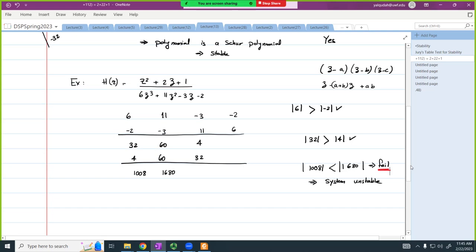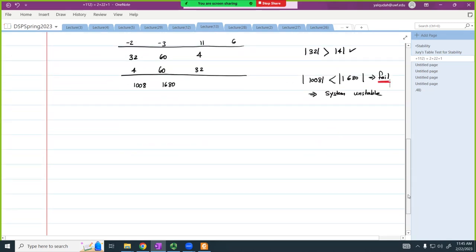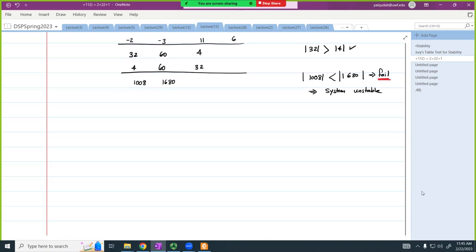Any questions? Now, when we do this in control with the Routh-Hurwitz, and probably those who took control, we've done the polynomial with the roots. Anybody remember when we have 2 roots, 3 roots, and then we multiply them, and we looked at the structure of the polynomial and saw the pattern of how the location of the roots translates into the coefficients? The coefficients of the polynomial are determined by the location of the poles.